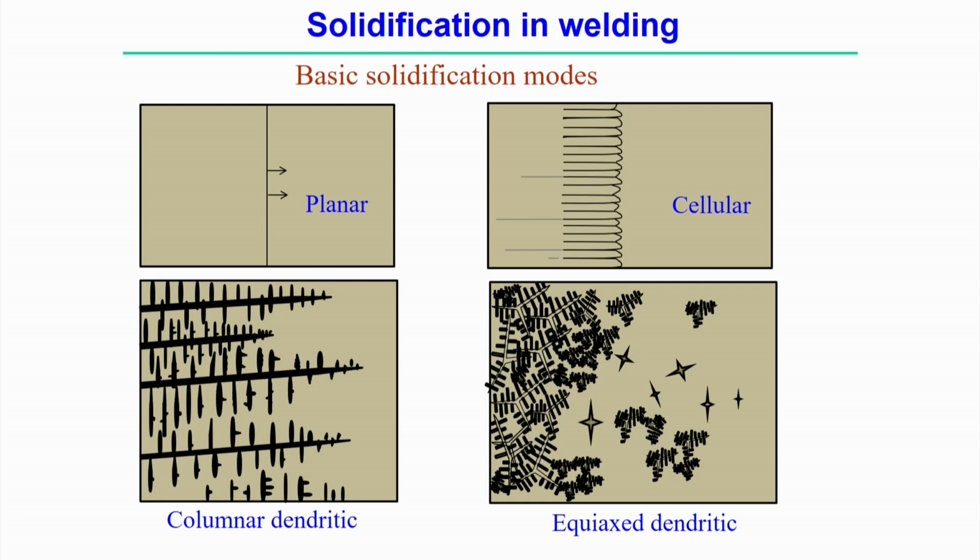Another is the equiaxed dendrite. Here the dendritic structure exists within one grain, and there are several positions with grains of almost equal size. Within each grain there may be development of a columnar type of dendritic structure, so the dendritic structure is observed within the equiaxed structure.